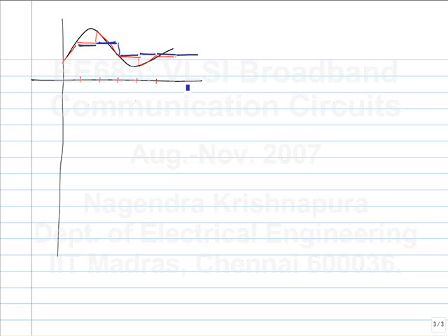In reality, what happens is that switching from one to the next is not instantaneous, so it takes some time. So this is a sample and hold, and if you put it through another set of the same stage, the entire waveform will be delayed by one clock cycle. Is this okay?